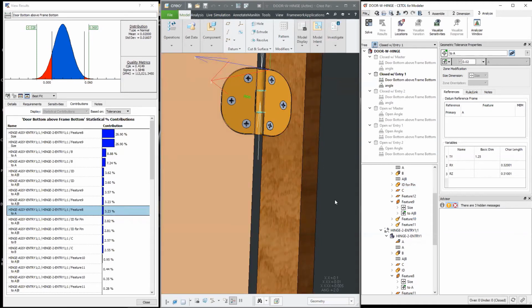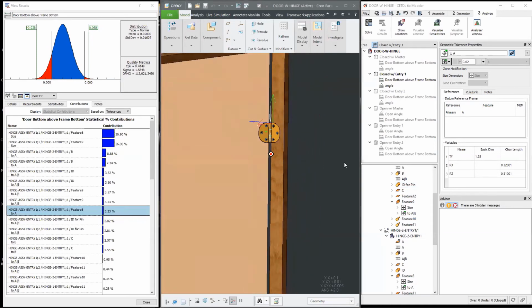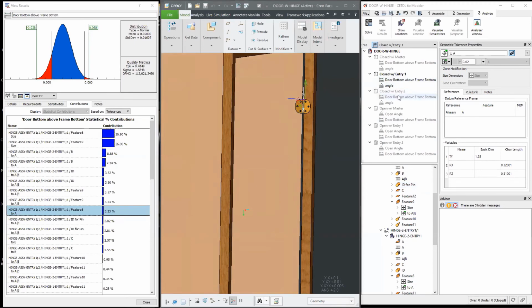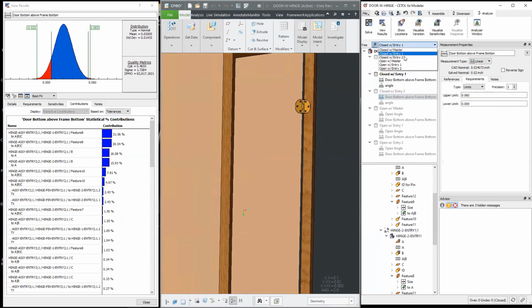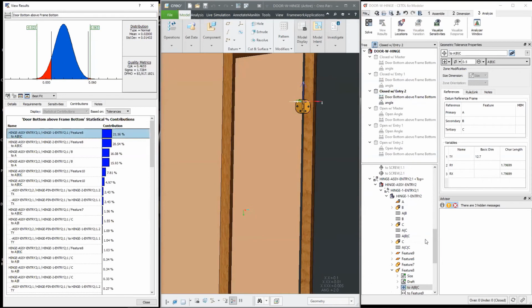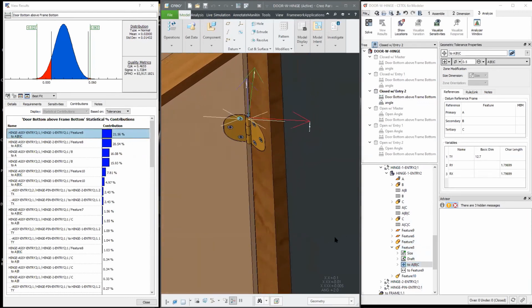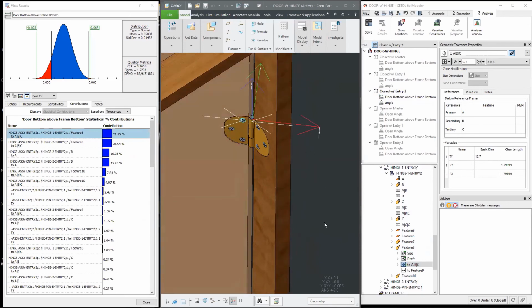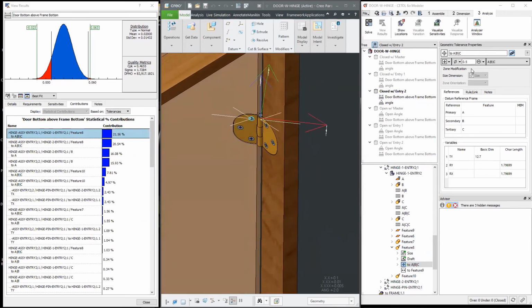All right, so that was the interesting thing on this particular one. If we go down and just show you the difference with the second entry, just look at what was driving the things there, because obviously there were some differences here as well. So the top contributor there was the position of the clearance hole. I'm sorry, the position of the cone, which I assumed in this case, because they combined the two, I went ahead and assumed that both the countersink and the clearance hole were positioned with the same.